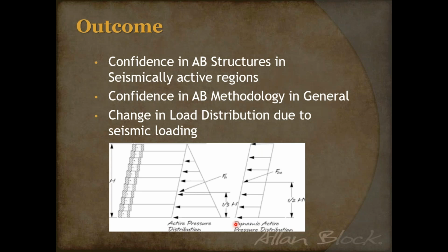And this was interesting. Remember I told you about the grouted connection that we had at the top of the wall? We don't do that anymore. Why? Because we don't see the seismic loads the way they originally dreamt them up. Here we're looking at a free body diagram. We got the face of the wall right here. We know that soils act like a triangle pressure distribution. So very little pressure on top. The deeper you go, the more pressure you feel. So the bulk of that soil pressure is at the base of the wall.